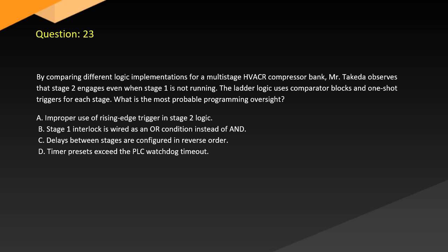A. Improper use of rising edge trigger in stage 2 logic. B. Stage 1 interlock is wired as an OR condition instead of an AND. C. Delays between stages are configured in reverse order. D. Timer presets exceed the PLC watchdog timeout.